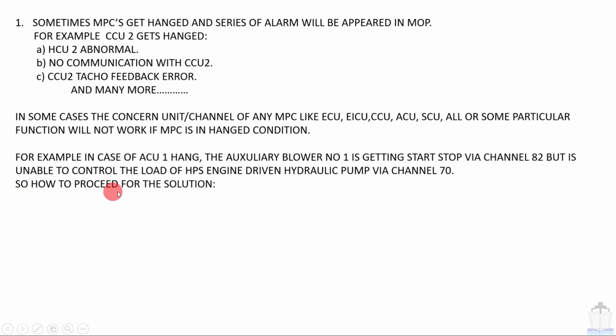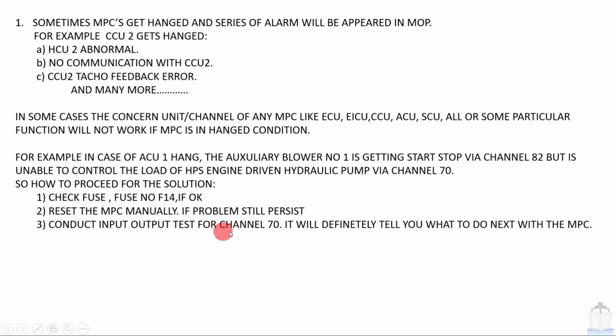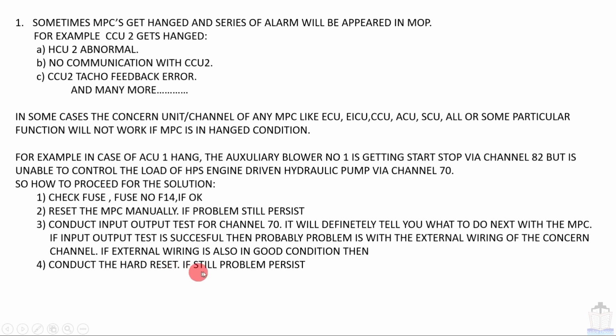Okay, so how to proceed for the solution? First, check fuse number 14. If okay, reset the MPC manually. If the problem persists, conduct an input output test for channel 70. It will definitely tell you what to do next with the MPC. If the input output test is successful, then probably the problem is with the external wiring of the concerned channel. If the external wiring is also in good condition, then conduct the hard reset. If the problem still persists, then change the MPC. This will definitely sort out your problem.